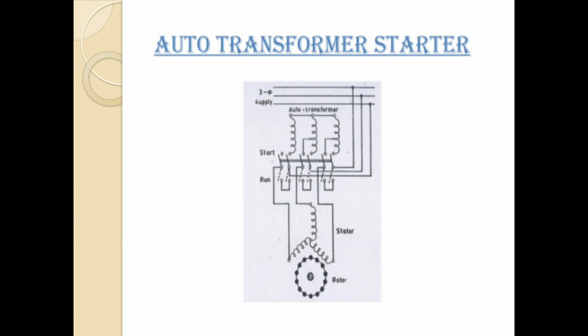Hence, the supply is switched off. Low voltage protection means that the under voltage relay coil is connected across the two lines. When the supply voltage goes low or fails, UVRC is de-energized and releases the handle to the off position.